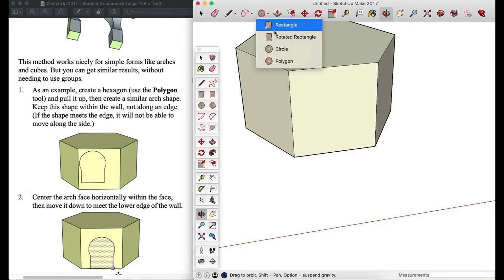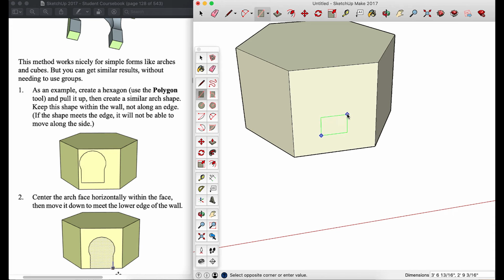Again, to do that, we start with a rectangle. Then I am going to use the 2-point arc to make our shape. I'm then going to delete the center line. I'm going to select our archway from the center point and start to move it. And as we move, I want to make sure I move it to the midpoint of the bottom line. So if you look now, we kind of have the same basic structure. We have our shape and we have our archway.